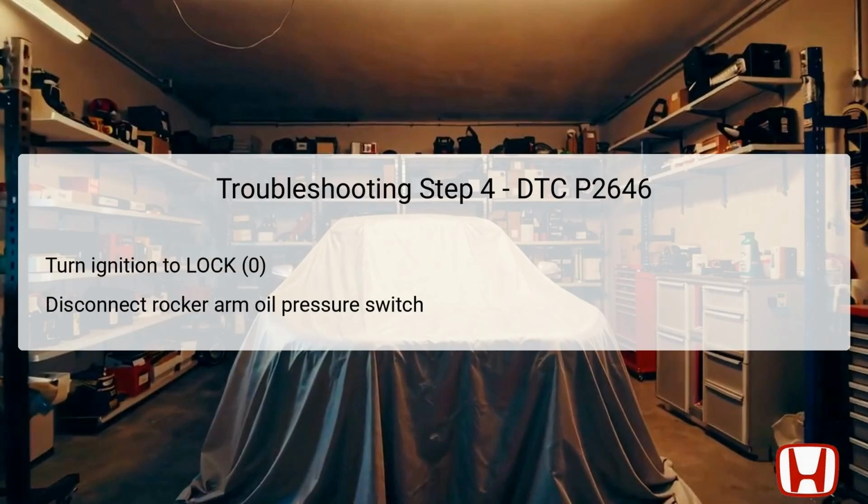Should the VTEC test indicate a malfunction, the next step requires turning the ignition switch to the lock, 0 position, to safely disconnect the rocker arm oil pressure switch. This is a safety measure to prevent any potential electrical shorts while working on the circuit.